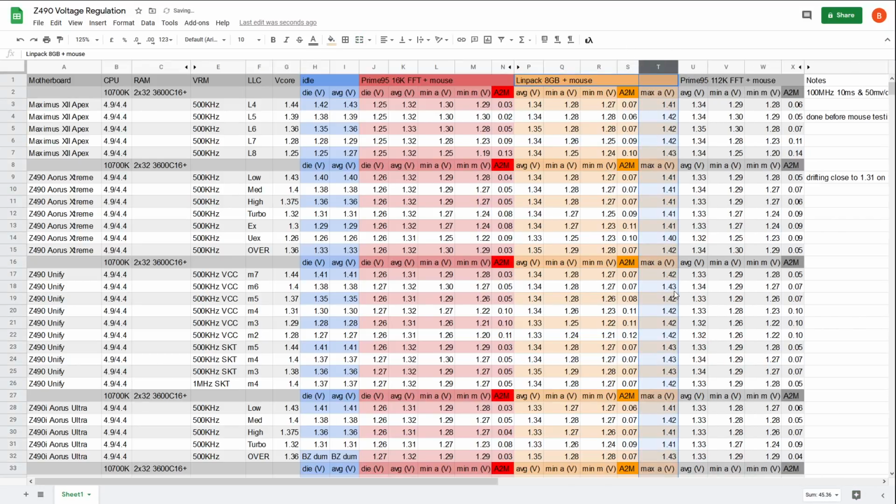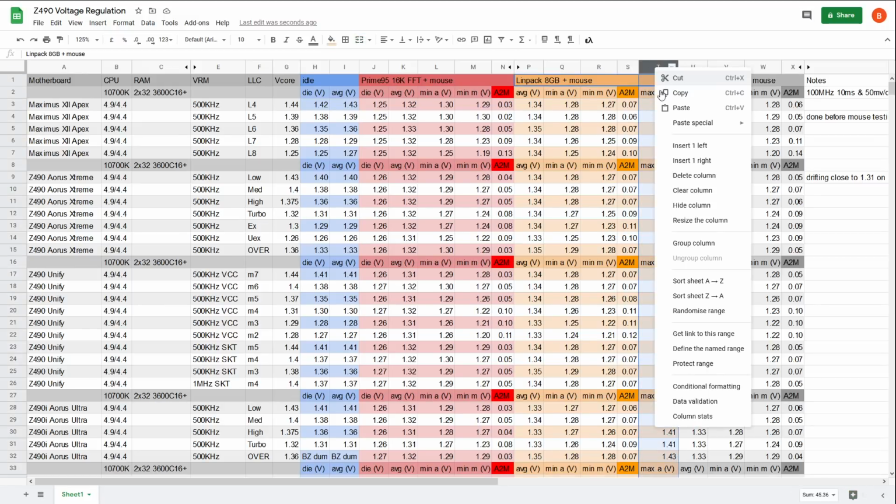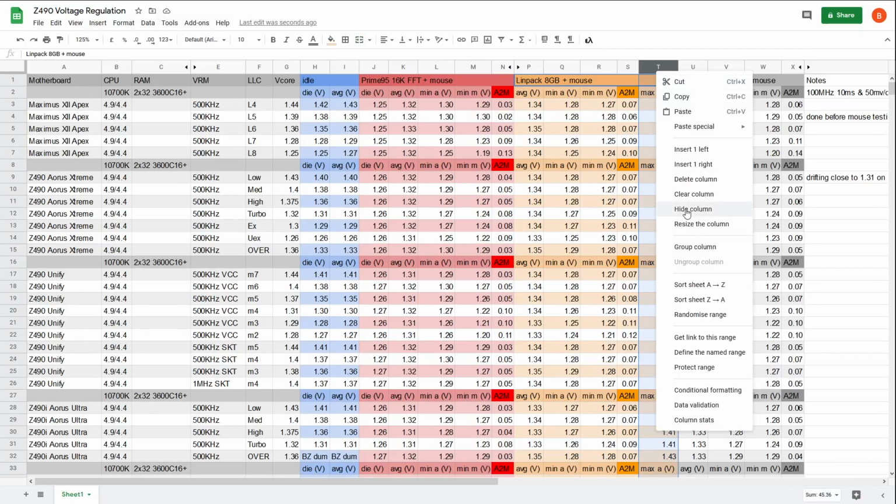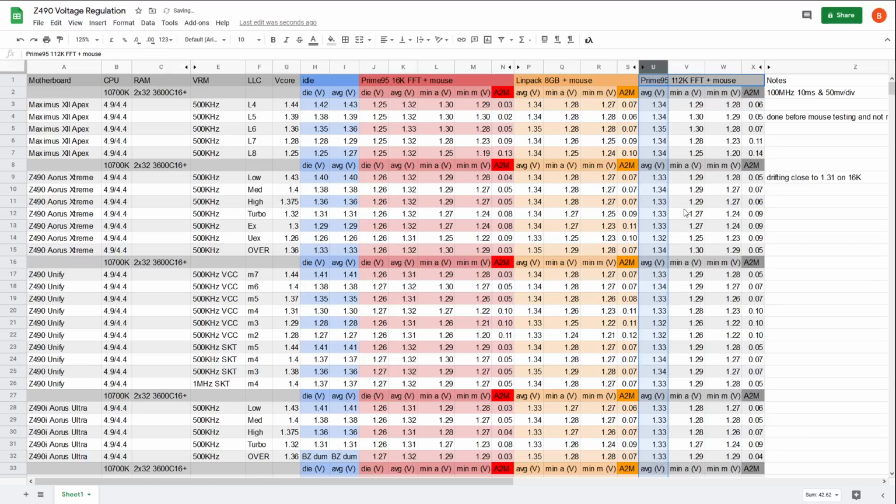And there is one downside to it: it raises the overshoot, right? Because it's pulling the average voltage up, it also lifts up the overshoot a bit. But it's still not like it's 10 millivolts higher than if you weren't using it. So it's not like, oh whoa, this is a catastrophe, there's so much overshoot. Nah, it just raises it a very slight amount, so it's not a big deal. So yeah, override mode is just great.